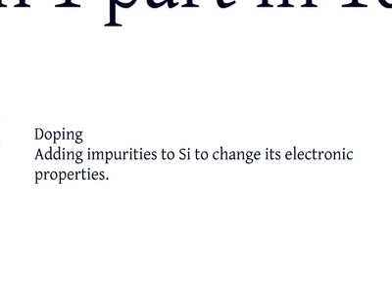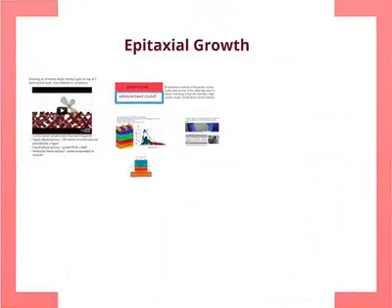Then, during this process, you can also add impurities. Like I showed you in the example before, we had arsenic, antimony, Sb, which replaced the silicon and gave it an extra electron, if you recall, in that example. You can do that during this pulling. So when you pull it, you can add impurities into the melt. As long as the impurity crystal structure is close to that of silicon, it'll get incorporated. And then, of course, you can control the conductivity.